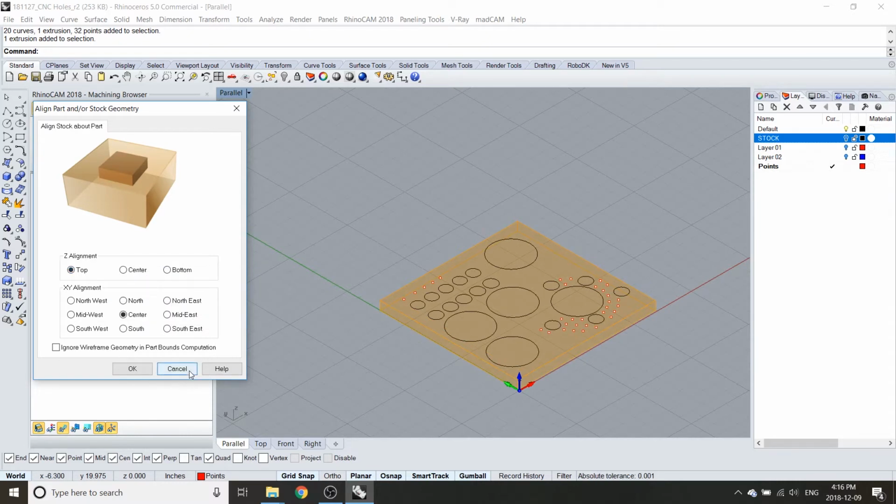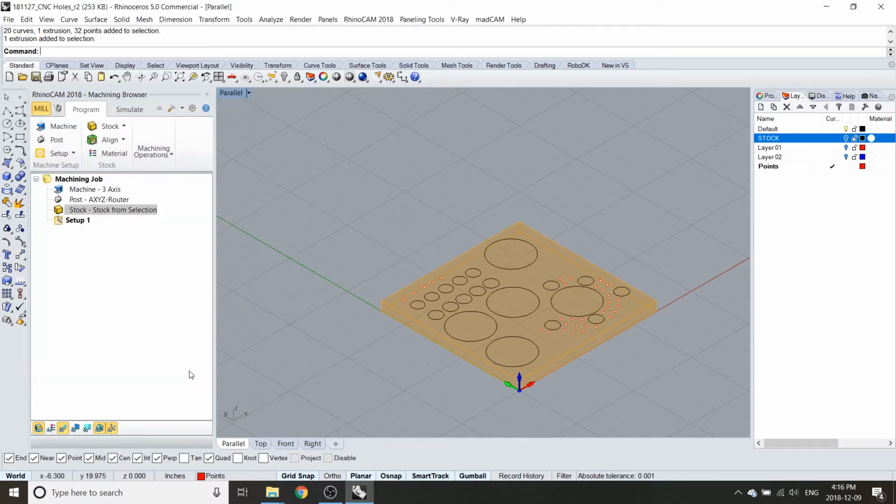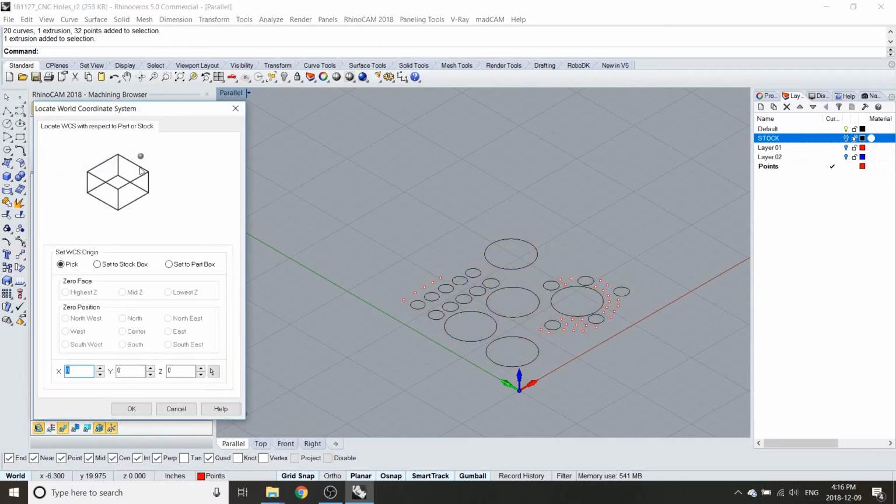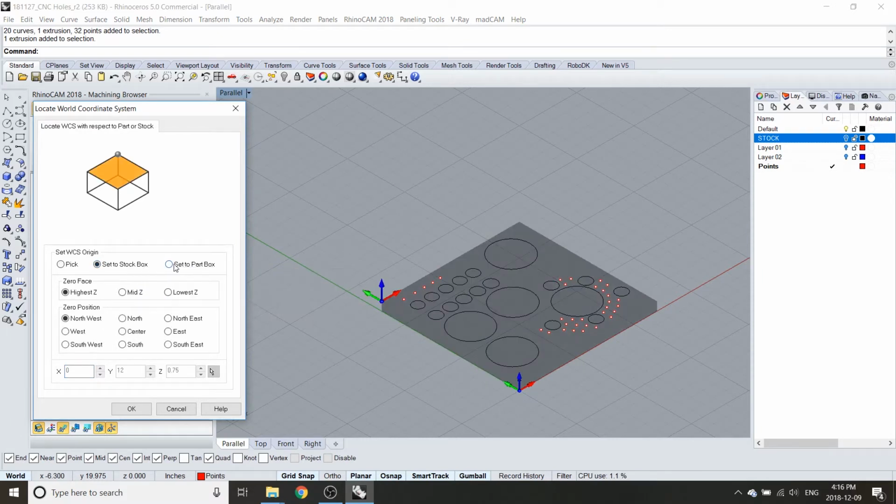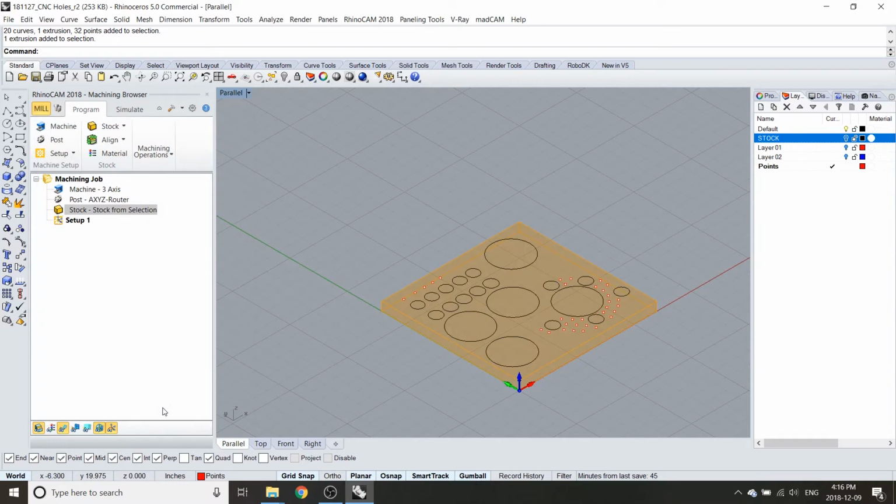Another aspect that will be set up is the World Coordinate Origin, or WCS. This location defines the 0 point from which all toolpath points are interpreted by the controller. This part will also be set up by the workshop staff. Alternatively, under Machine Operations, the button Work 0 can also be selected to define the Work 0 origin.